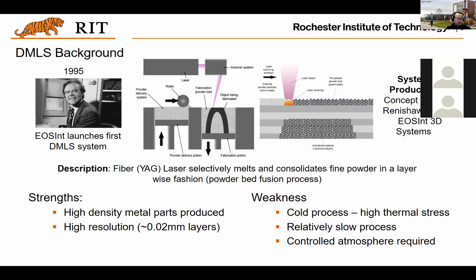And basically the strength of this process is it produces parts with a high density. Also, the resolution is pretty high, usually 0.02 millimeter for one layer, right? That is a really thin layer. And it turns out it will make the part with a very high accuracy.